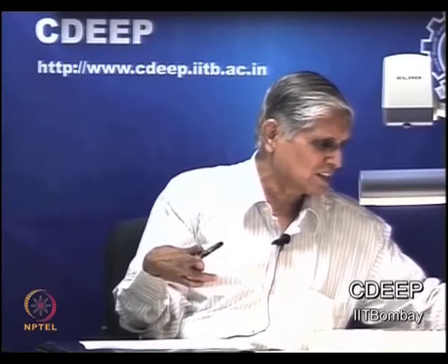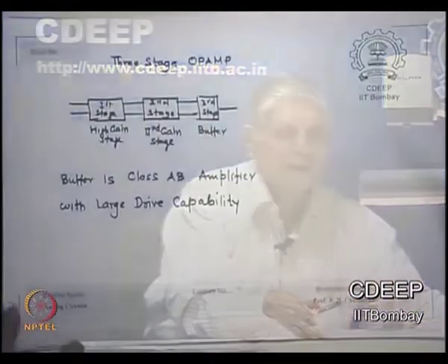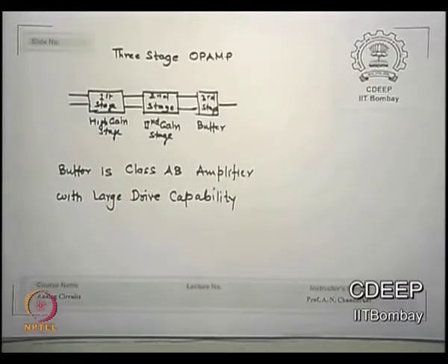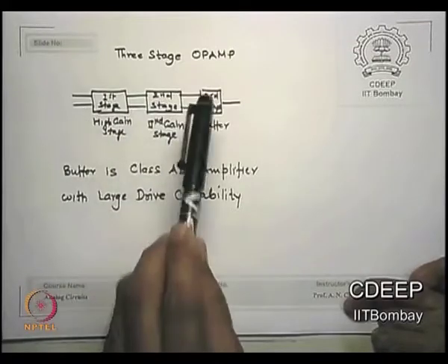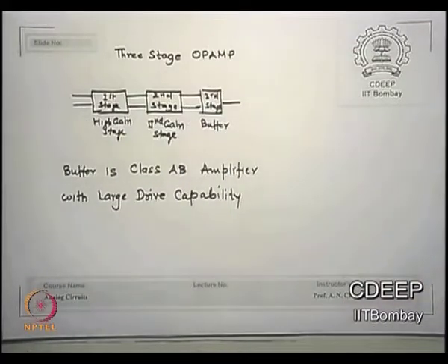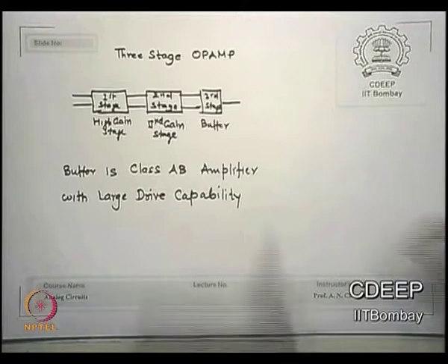Okay. So this is essentially what I was trying to say. I may not go into details about this OPAMP basic internal circuit. As I said, the 3-stage OPAMP, which is the real OPAMP, has the single common source, high gain stage, followed by another circuit called a buffer, which is essentially for large driving of the output loads.